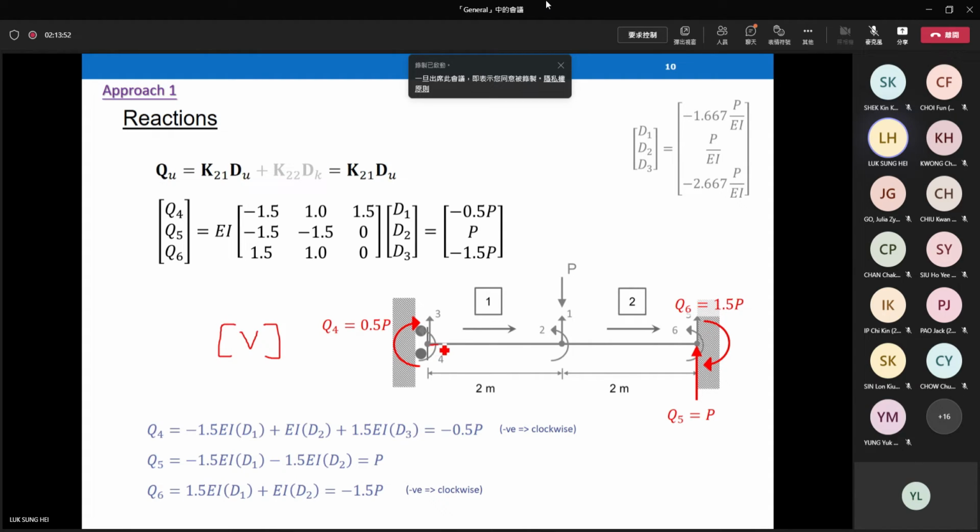So we believe that we have horizontal zero values in our shear force diagram. And then at the middle, we meet our first concentrated force. So we have a downward jump. And then no force at the middle. No force means the shear force diagram remains horizontal. And then finally, you close the diagram, and we meet another upward force, and you can see a sudden jump on the top.